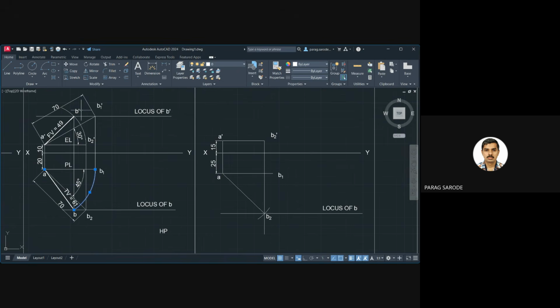Yes, sir. So let us draw that. With the same center A, with the radius equal to this, I will press and hold control like this. Once I click, I remove my hand from the control button of the keyboard. Then I will join this. And what's the point I will get? B. Correct. So I will copy this here.